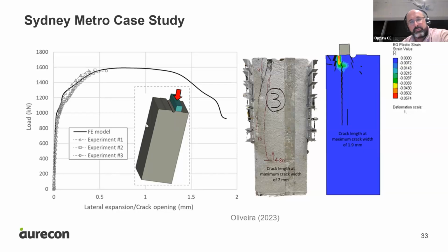In the model we can directly get the crack width. Obviously, this is ULS, and in service we designed the cracks to be smaller. Generally, when designing fibre-reinforced concrete, we have been working in Australia with an allowable crack width of 0.2 millimeters in our tunnel linings.